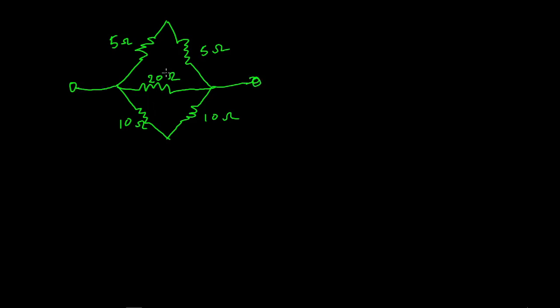This circuit may look kind of complex, but to solve this kind of circuit, it is advisable you redraw your circuit, and in your redrawing, you restrict the layout of your resistors to either horizontal or vertical positions. Now, if you want to redraw it, it is more so advisable you label the joints for easy identification. So we are going to label these joints A.